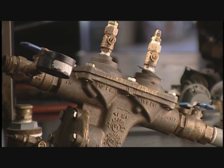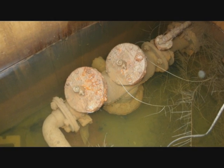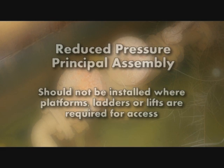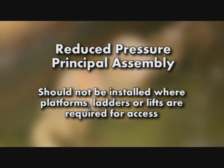RP is an assembly designed for both high and low hazard applications. RPs must not be installed in pits where the relief valve could become submerged. RPs should not be installed where platforms, ladders, or lifts are required for access.